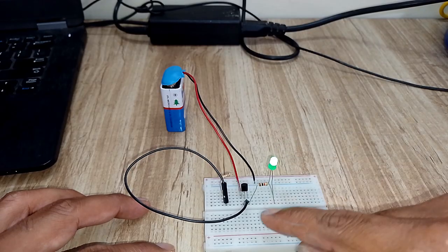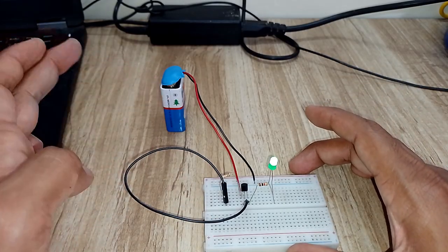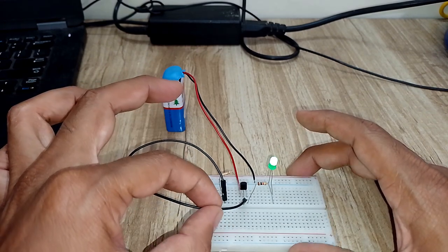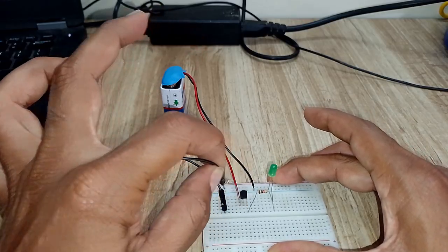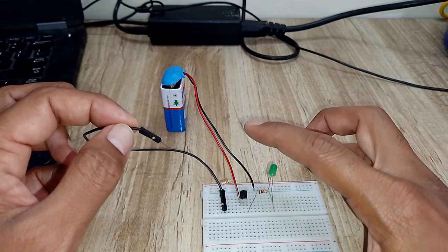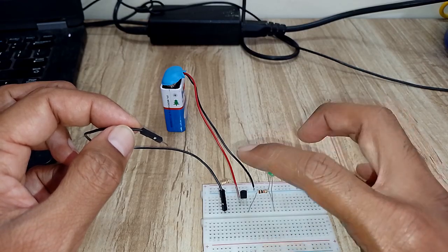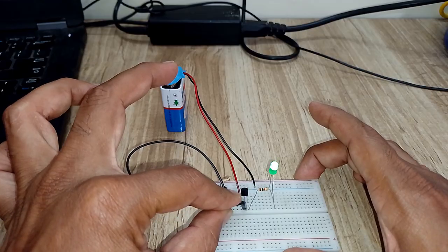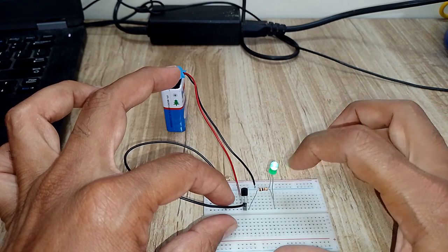Which means now your transistor is on. Now we need not take off the supply to switch off the LED. The moment you remove the base, see, I am removing the base from your transistor. The base is removed, so the transistor is switched off, which means no current flows from your collector to emitter. We have connected the LED at your emitter, so no current flows and the LED is switched off. The moment I connect the base, the transistor gets biased and current flows from collector to your emitter, so the LED glows.